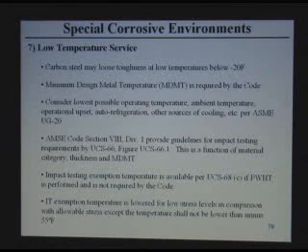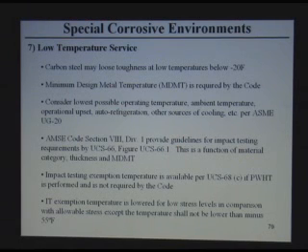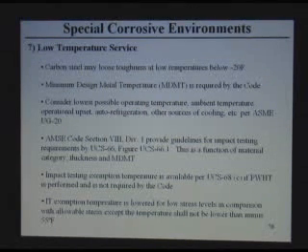Each equipment now should have a minimum design metal temperature, we call it MDMT. It is required per code for any pressure item, piping, or equipment. If you know the minimum design temperature, then you start finding what best material to use. Generally, below minus 20 F minimum design temperature, you start using low temperature carbon steel, which means carbon steel which has been impact tested to make sure it is tough enough at the minimum design temperature.